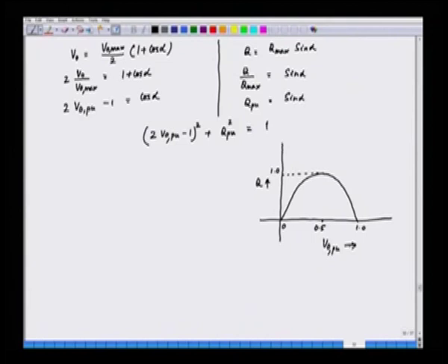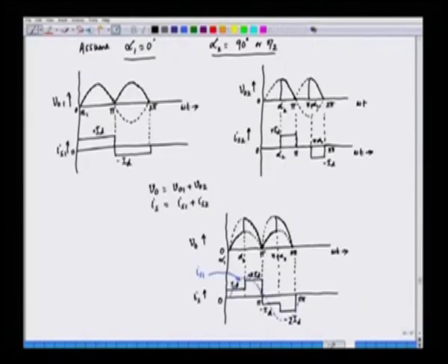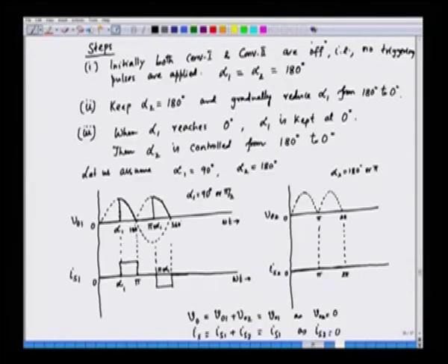Now, when we have two single stage converters, each converter is going to give us half the output voltage. If the output voltage is, let us say, 400 volt DC, the capability of each converter here will be 200 each. Now, if the converters give us half the output voltage, the input voltage is also reduced to half. So, we can see this in the diagram here.